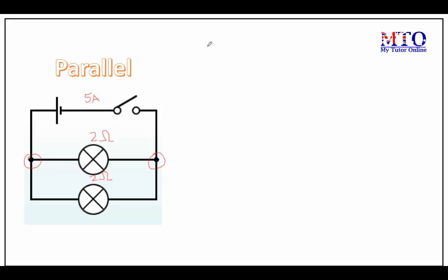to give you a better understanding of how this works. The current in a parallel circuit is actually different to what we just learned in the series circuit. As I've already shown you, the total current is simply 5 amps. However, when the current travels through, it splits right at this breakpoint, as is evident, and becomes 2.5 and 2.5. This then reconnects here and becomes 5 again.